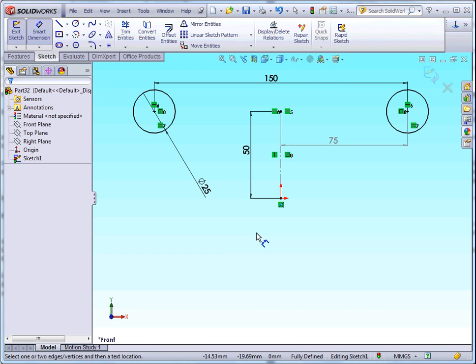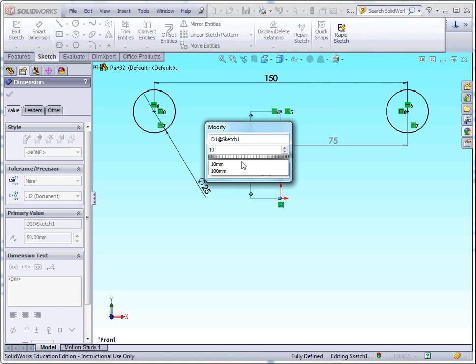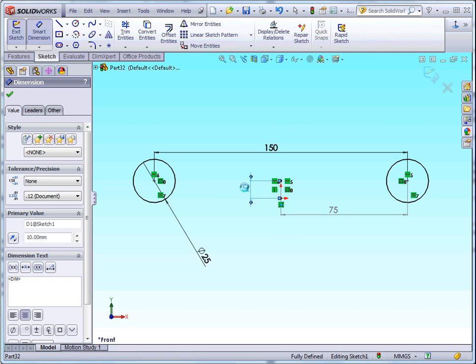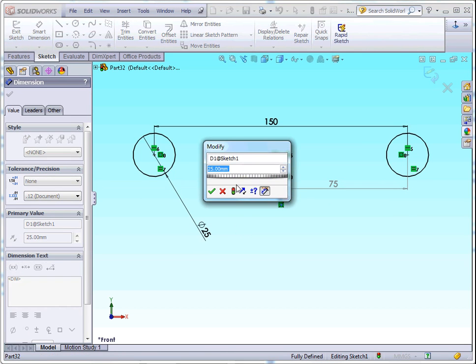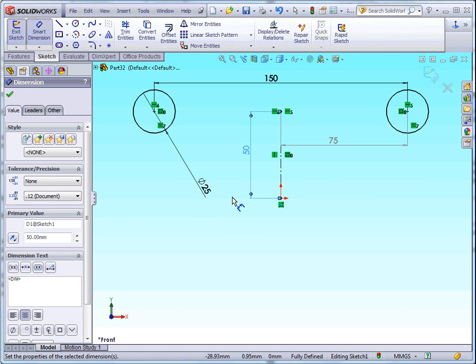If the vertical hole position changes, altering one dimension will move the two or as many holes as there are in the pattern to the new position. If the hole diameter changes, altering one dimension will alter the diameter of all the holes with the equal relationship.